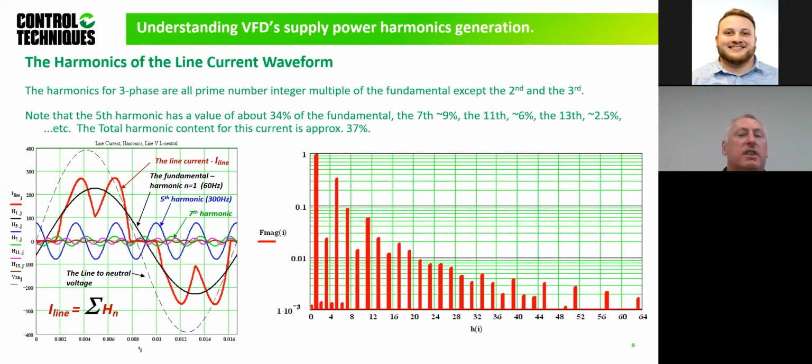Okay, so if you look at the harmonic spectrum of that, it's based on the pulse number. Again, we saw a three-phase bridge earlier on. It's got 6 diodes, 6 pulses of current. And as we go along this presentation, the pulse number is important because it tells you what harmonics will be existing on that distorted current. So in this case, 6 pulse, we're looking at fifth and seventh, 11th and 13th, sorry, I'm getting a little confused myself here, 17th and 19th, and so on. And this is a diminishing thing. So you can see the currents diminish down with the order of harmonic frequency, okay?